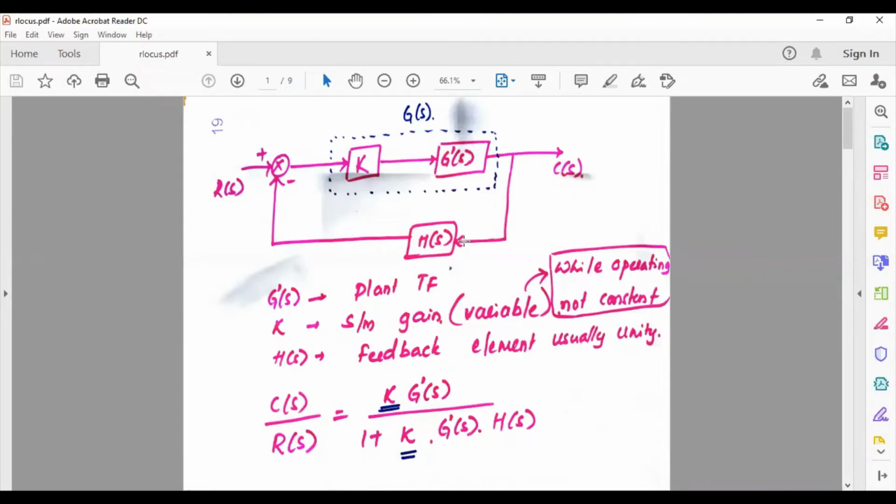Eyes will act as a sensor, and pedaling, your legs act as an actuator. Okay, actuator and sensor, you are already aware. An actuator is something that causes a change, like a valve connected to a DC motor. When a DC motor receives some signal, it rotates the valve. So we can call a simple DC motor an actuator.